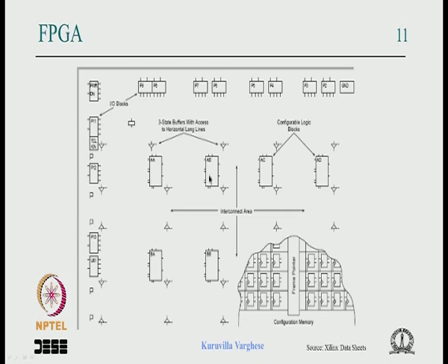There are logic blocks which consist of combinational circuits and flip flops. There are interconnect wires, but underlying is a configuration circuitry to configure all these, so you shouldn't forget about that. There is a lot of configuration overhead in terms of addressing these switches and programming them on and off.